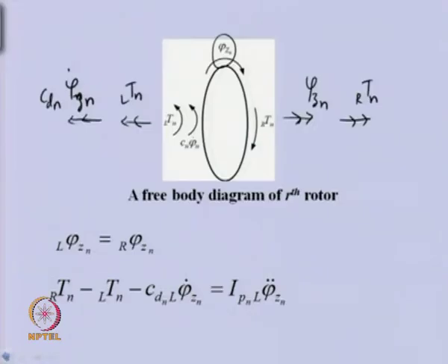So, if we substitute this assumed solution in the previous expression, you can see that the angular displacements have single derivatives and double derivatives also. If we take the derivative of this with respect to time, because this is independent of time, only this quantity depending upon time will get differentiated.